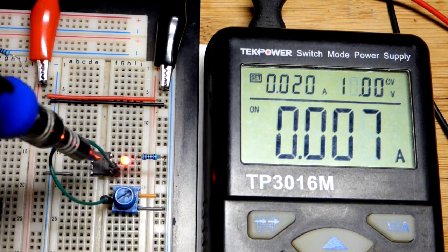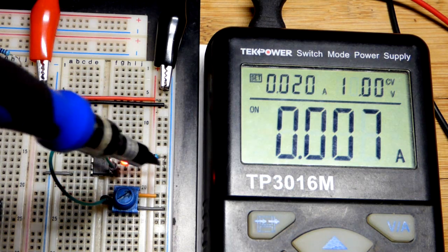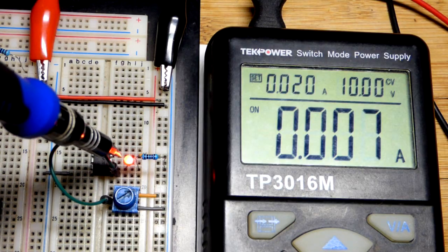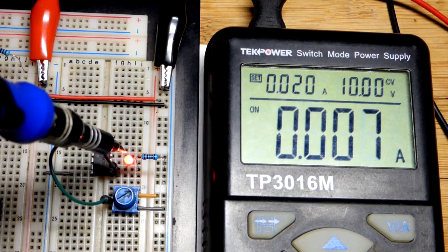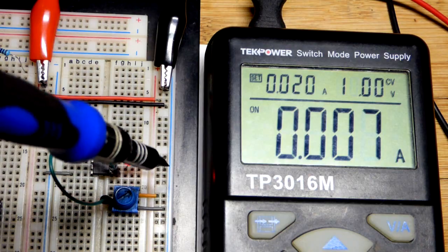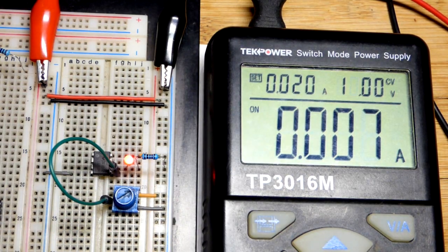When I set this up, first off, the LED drops a couple volts. So the most we could get is 8 volts across the 1000 ohm resistor. And then the output probably only gets to like 8 volts, approximately. So we lose a couple with the LED, probably only get about 6 volts approximately, maybe 7 volts across that 1000 ohm resistor for 7 milliamps of current.